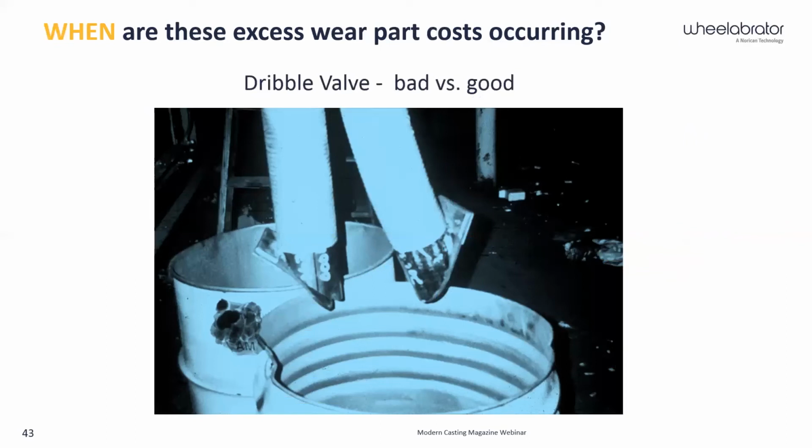Problem is now when my dust collector is drawing air, I'm actually drawing ambient air from down here. So I'm not pulling all that air across that separator curtain. I'm pulling it up this tube, so I'm not as efficient at the separator curtain. These things are all designed so that with a certain amount of weight of the fines, they kind of burp. They'll slowly open up to release the trash and contaminants into a barrel like that.